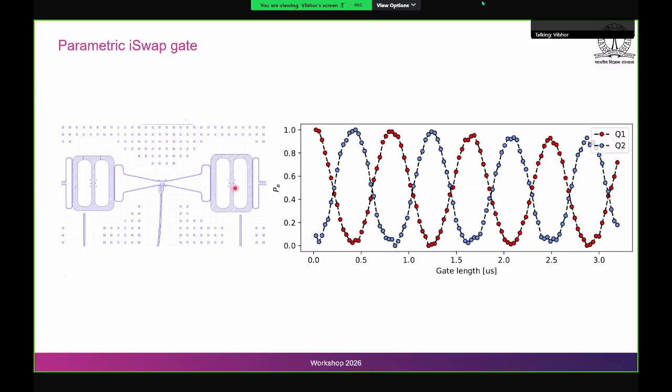And what you see here, there are 2 qubits, one on this side. So these 2 pads are the capacitances, and then one can make junctions in between. Similarly, this is another qubit pocket where these 2 pads are the capacitances and a junction in between. And what is implemented here is that there is another qubit in between, whose frequency can be modulated by sending a fast flux through this line.